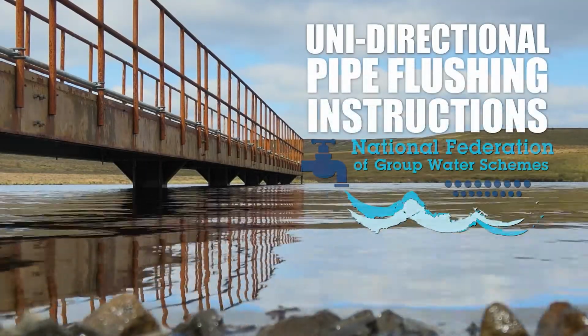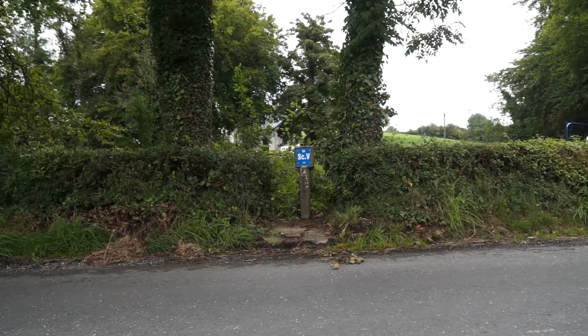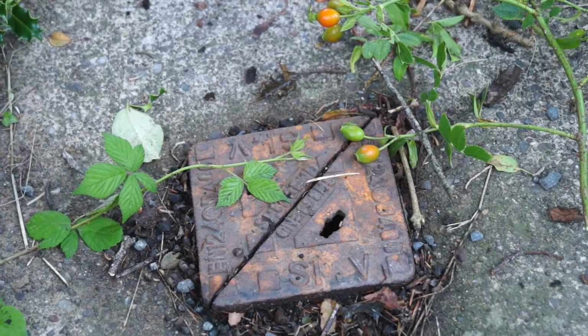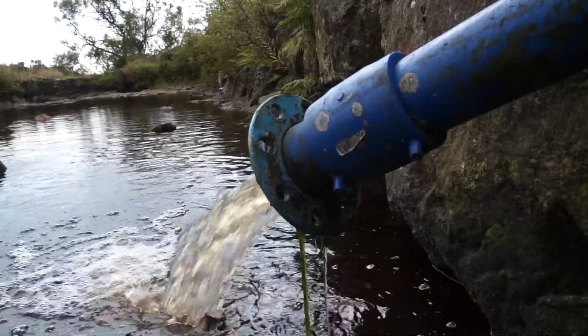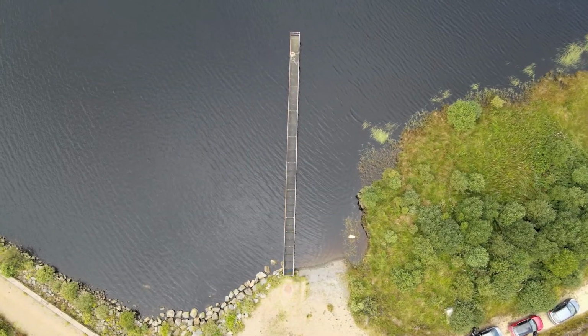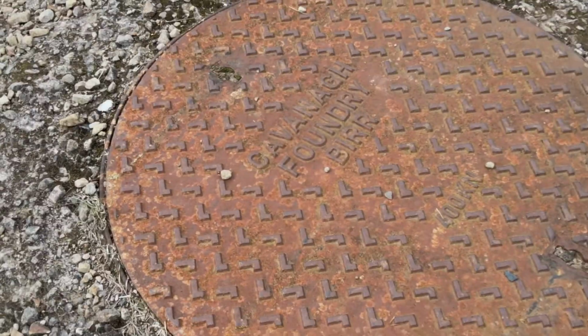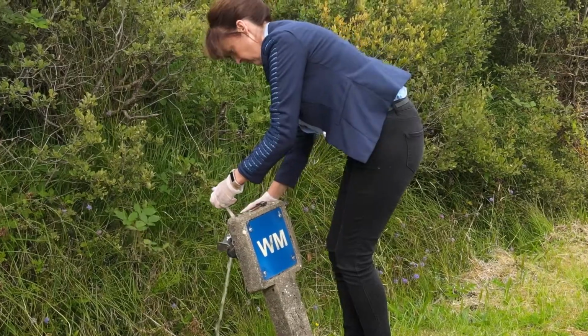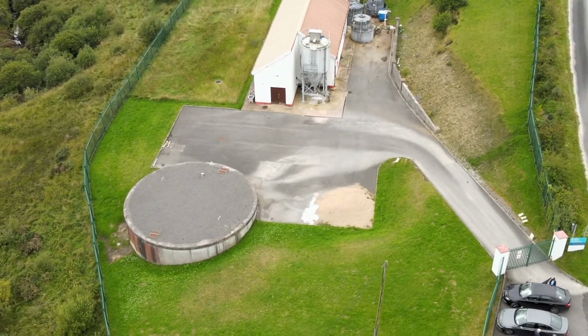The National Federation of Group Water Schemes recommends the following procedure in unidirectional pipe flushing, UDF. The key to a successful UDF program is maintaining your assets before you flush a segment. Do a physical check on all the pipes, valves and hydrants in the segment. This gives you the opportunity to check and repair each asset before the UDF process starts.